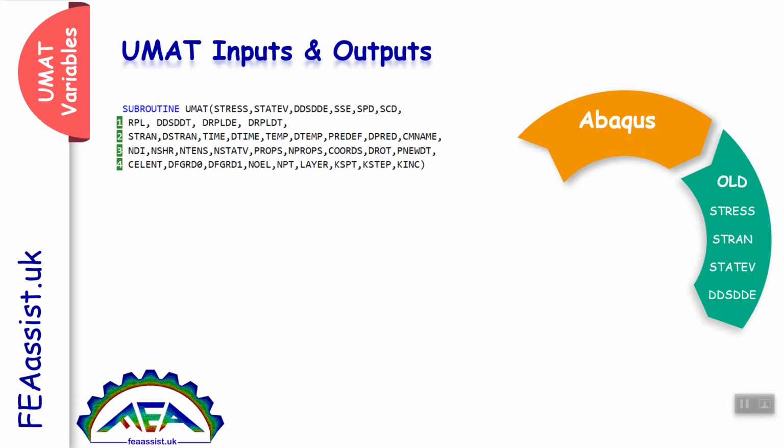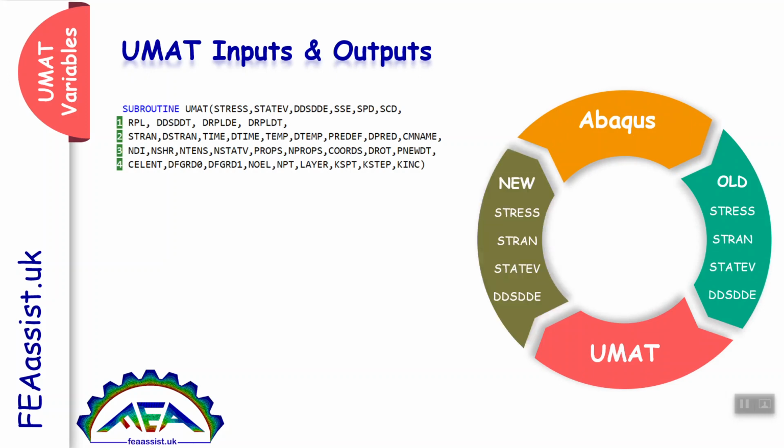transferred to the UMAT. In the UMAT, we need to write some equations based on our constitutive behavior to recompute these variables, all the variables, and return all of them back to Abaqus. This is how Abaqus and UMAT interact with each other, which is necessary to write a well-working UMAT.